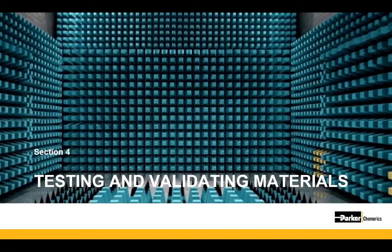Our last section before the application examples is all about testing and validating of the material. So volume resistivity, shielding effectiveness, lap shear strength, and peel strength are the key properties that most people will test for or design around in order to validate a program requirement. Each of them typically has a different test procedure and often an industry spec surrounding it, such as IEEE, ASTM, or a military specification.